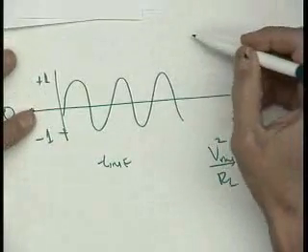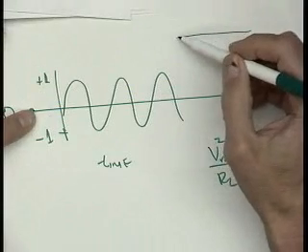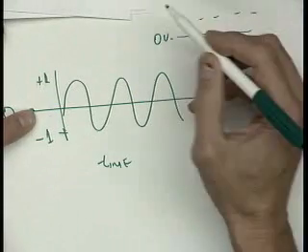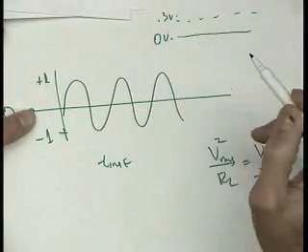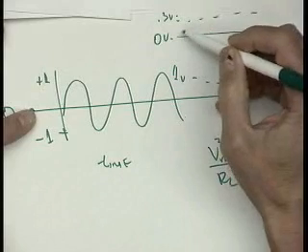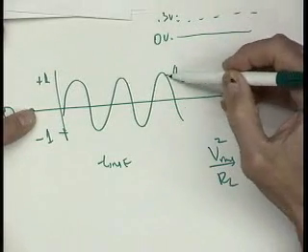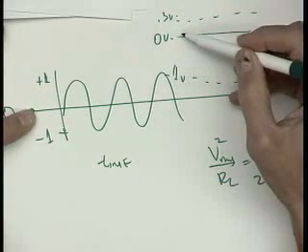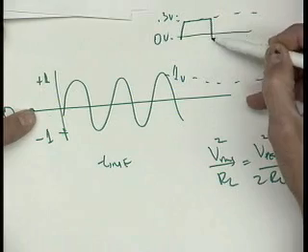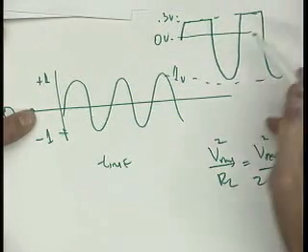Something I didn't say before. Let's say you designed your circuit so that here's 0 volts, and the clipping point was at 0.3 volts in the positive direction and 1 volt in the negative direction. If you put in a sine wave of 1 volt in size, it would go up and saturate at 0.3 volts, and then have a nice swing at the bottom, and then go up and saturate and go down, right?